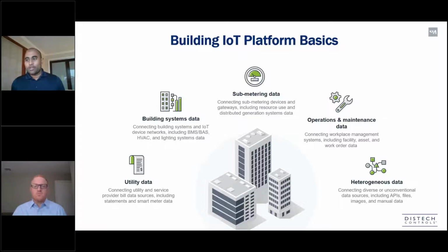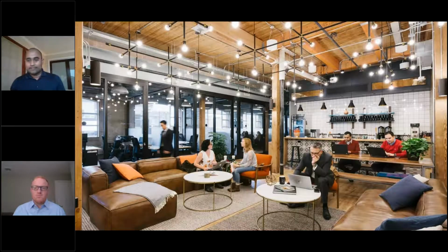With that said, we went straight into IoT platforms, which is an elevated view of a building or infrastructure, where the BAS data is only one component of an IoT platform. At this level, the building owner wants to see utility data and sub-metering data. They want to see different asset tracking aspects. For example, the building might have generators, wheelchairs, or forklifts. They want to be able to track those assets and see their characteristics along with the building data, the sub-metering data, and other data sets as well.